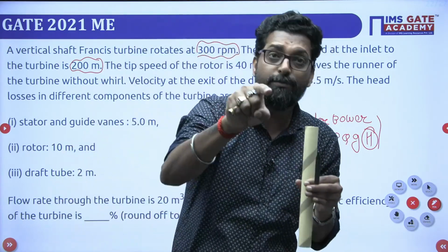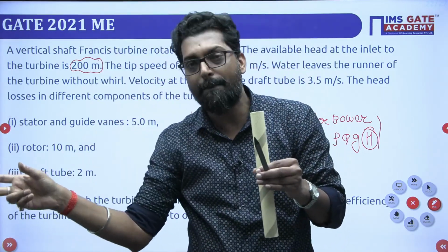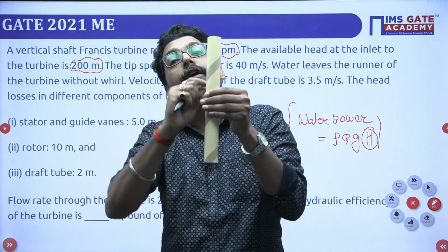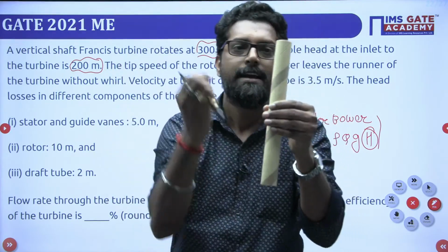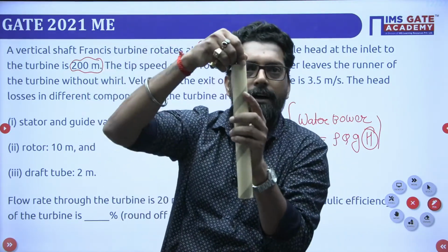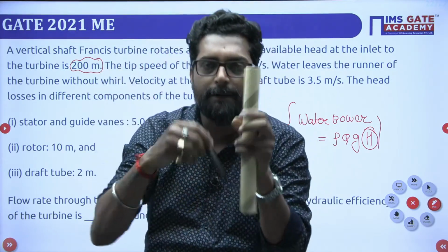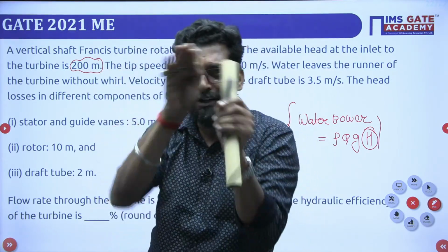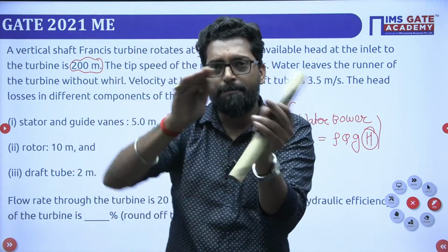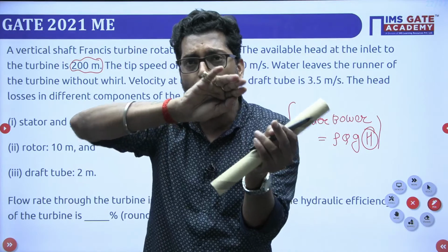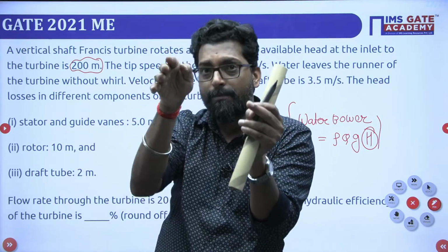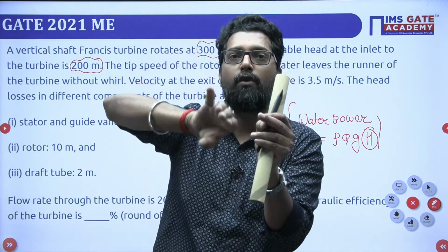But what is the case of the Kaplan turbine? The radial entry is pure radial, but the exit is pure axial. That means like that, it is in here, and it is axial. That means there is no gap, there is no time span. That means there is no possibility to rotate the stream while it is engaging in the rotor of the turbine.